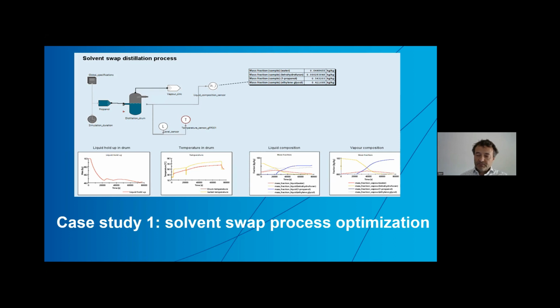What we will talk about in this presentation is how the same model is used to actually control this process in an automatic way and with flexibility to either run the process so that you minimize batch time, or you minimize solvent or energy consumption, or you actually have an economic cost function, which weighs the cost of materials, the cost of utility, but also the cost of occupying the asset before it can be used for the next batch.